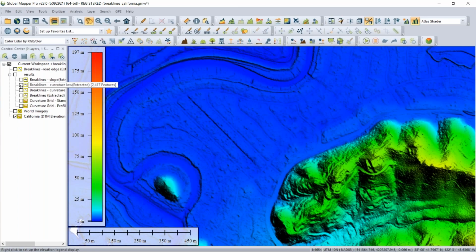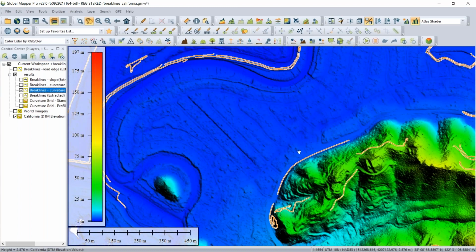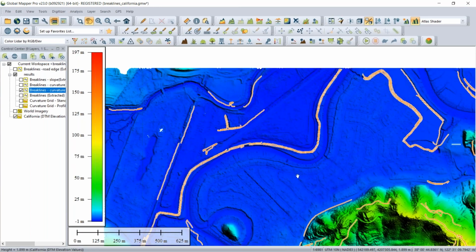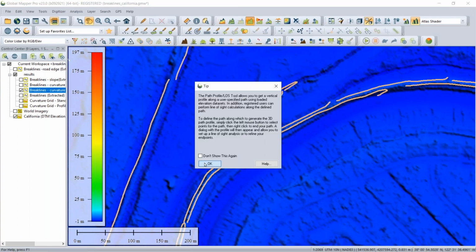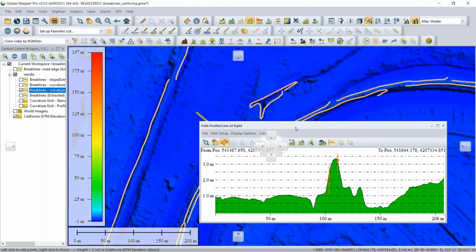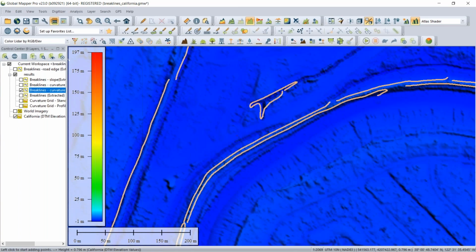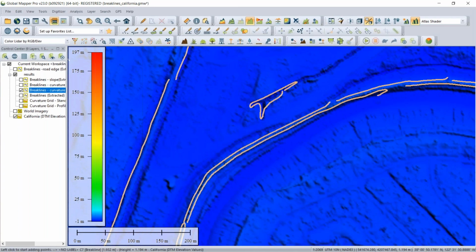Let's actually show this one first. Looking at only the longest lines here and quite a high tolerance, this has allowed me to pick up this levee feature here. This is an embankment or a levee around the top of the river. It's quite a drastic break in the terrain. Let's do a profile across this again, just so you can see this. Across this profile, I've been able to capture those break lines, making sure that I'm drawing on either side of that levee feature here. So we have break lines now capturing that data.